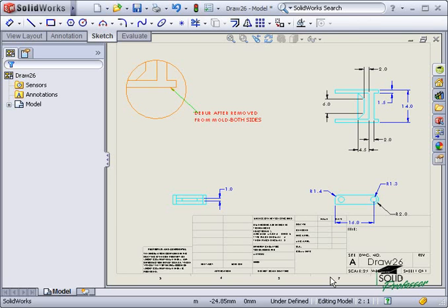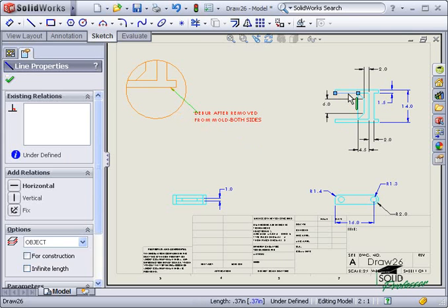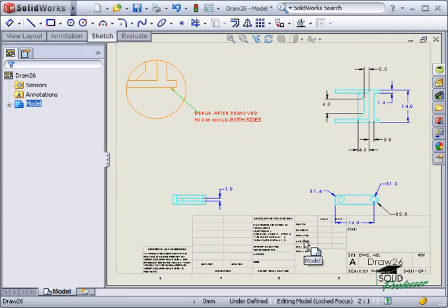As I mentioned, when we were going through the import options, there are two modes in SolidWorks 2D environment: Edit Sheet and Edit Sheet Format. Notice right now I can select any of the line work from the main views in the drawing, but if I try to select anything in the title block, SolidWorks won't let me. That's because we added the title block layer to SolidWorks sheet format.